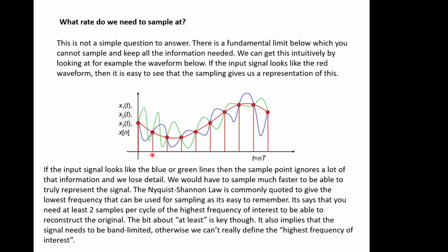But that can't be true for lots of other systems, such as communication systems and things. So you have to think about anti-aliasing, and the filters that we've looked at are very important for that. And the cutoff frequency of the filter and the response of the filter is very much dependent on the sampling rate that you wish to get away with.